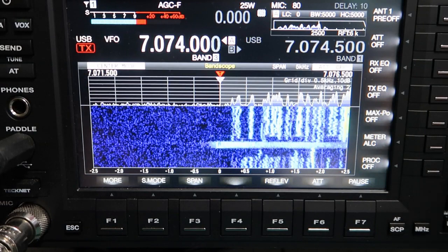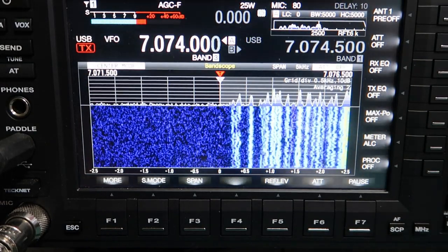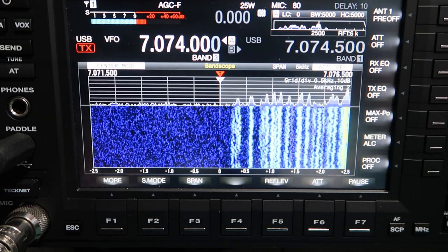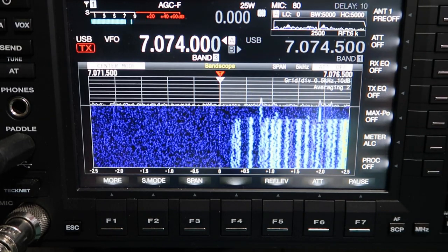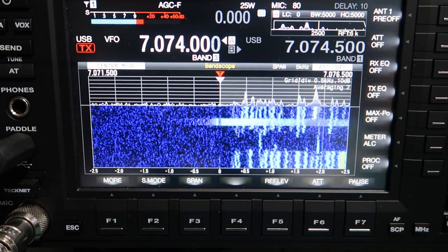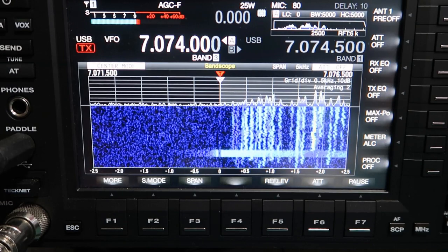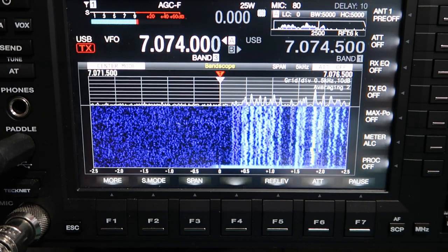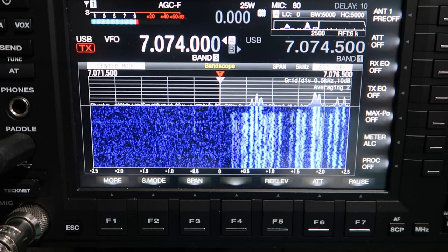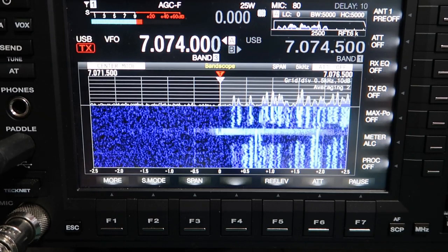So the third thing we need to worry about is configuring RTS and DTR lines. Now, it all sounds a bit complicated, doesn't it? But basically, in the early days of RS-232 communication, a serial port, which is the 9-pin traditional type, or at one point it used to be a 25-pin connector, includes 2 lines which we originally used for hardware handshaking. RTS stands for ready to send, and DTR, I think, stands for data terminal ready, although I might be wrong. It used to be used for the handshaking, but these days that's not used very much, and in the amateur radio world we use them for various other things.